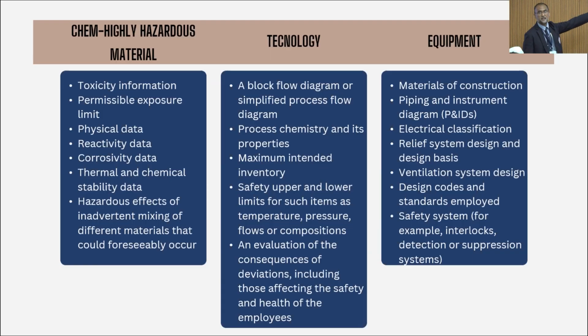Technology, this is part of design and in case of recovery. So you need a block flow diagram, the process chemistry, and the maximum intended inventory. Make sure you know how much you have. Above a certain threshold, you might have to report it to authorities. Safety upper limits: temperature, pressure, flow, composition.